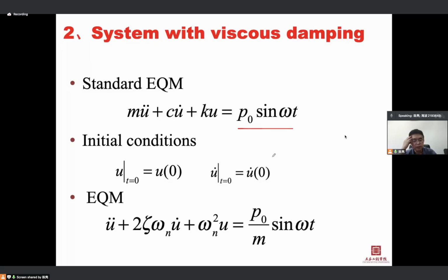In my opinion, the whole of structural dynamics, at least what we have learned here, is about how to use resonance and how to avoid resonance. And this is one way. When you design a structure, let's say we know the loading, like wind or earthquake, and the dominant period of the wind, let's say, is 1 second.